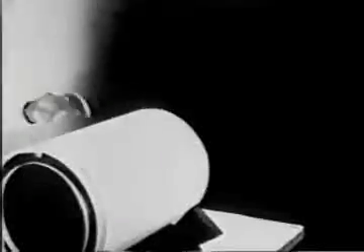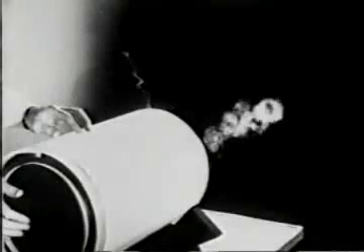Smoke rings also illustrate the vortex laws. You've never seen a smoke ring which is broken somewhere, nor will you ever see one, because vortex lines can never end. The fact that the smoke ring propels itself shows that the vorticity is locked in the fluid, for each element of fluid is propelled forward by the induced velocity of all the other elements of the vortex, and so the whole vortex is convected by itself.